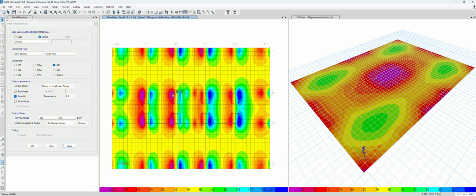So you see that at the intersection of the wall, it has something relatively more than 212 PSI. You see that minus 274. So this is a very local concentration. We need to evaluate something. Is this really practical or realistic? If you think this is a little bit exceeded, instead of just tackling locally, you may sometimes consider what if this is kind of average along this. If this average may be okay, then I think we may be okay.